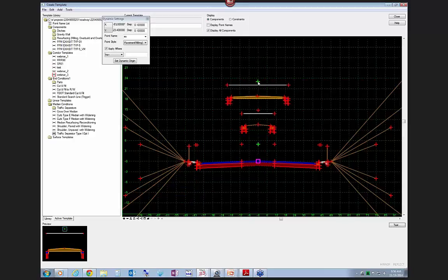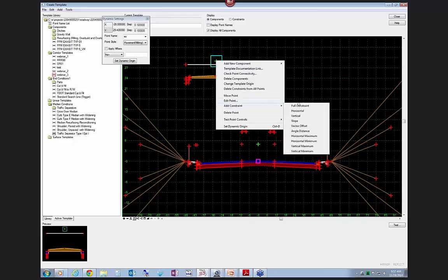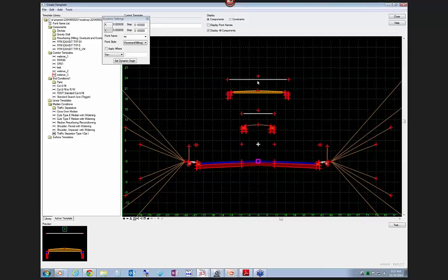And I'm going to drag it over to the center line, and I could put it over here if I wanted to, except I don't want to have this affixes checked on when I do that. And my other one is probably messed up because I did actually do it that way. So now when I drag it over here, these already have the affixes checked on. And in order to line this up with my median, I'm going to do the same thing. I have my center line point that holds everything in the middle. So I'm going to right click and do an add constraint, full constraint, pick this center point, and then set the value to 0 and to 20 in this case, because my first one was 10, my second one's going to be 20. As soon as I choose OK, it moves it over here.